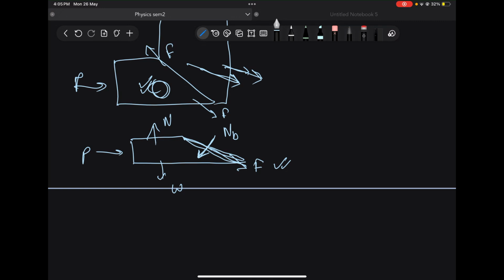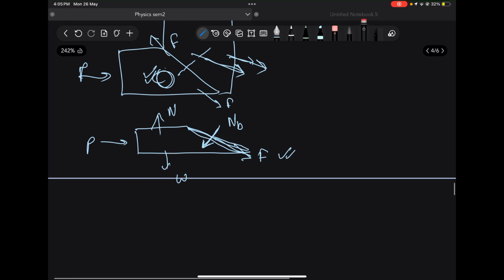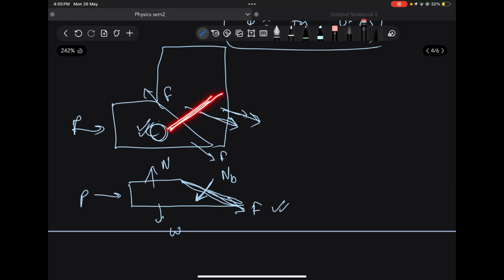However, I do think that taking the angle of tan and simply considering that, let's say, this is the perpendicular face, if this is the perpendicular which I draw, the reaction force should be applying R1 to this block, and if I were to consider this block, the reaction force will be applying something like this, R2. And solving it in that way, considering the angle phi, is much easier and will give you the answer in a way simpler form.